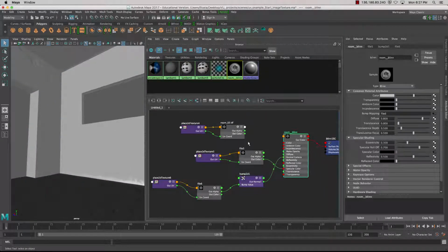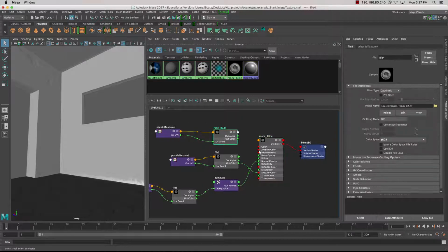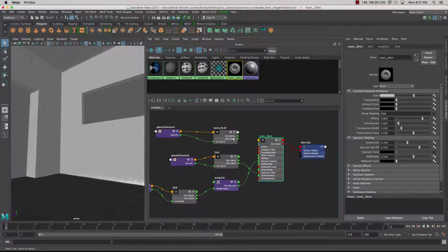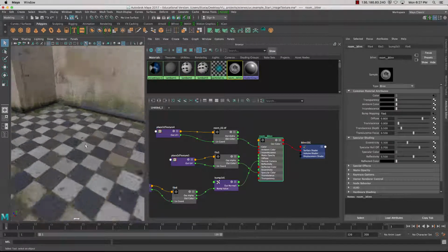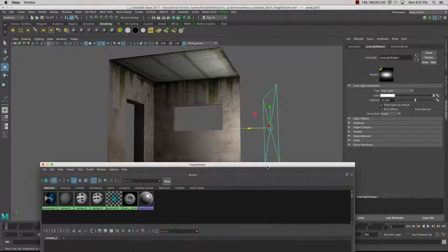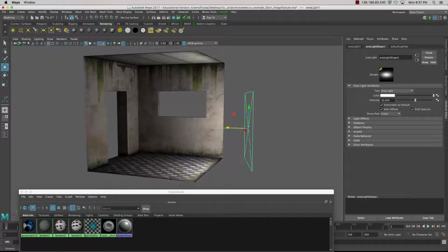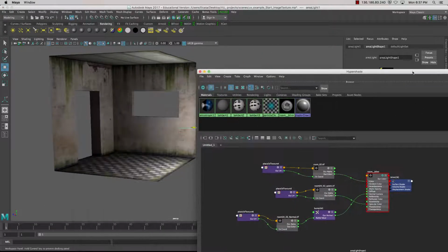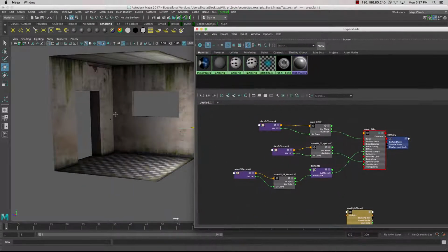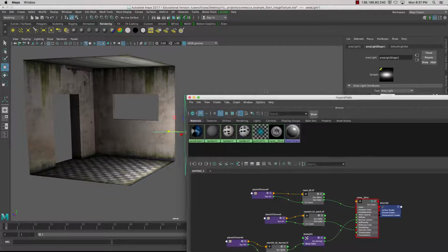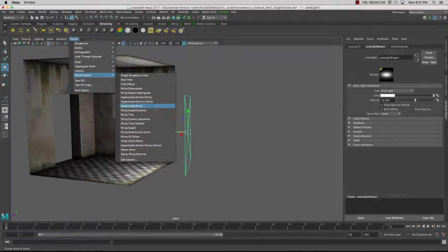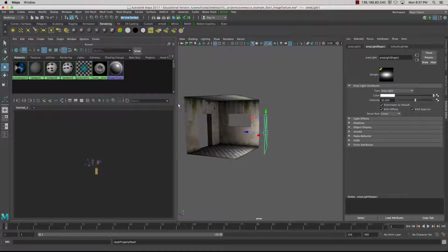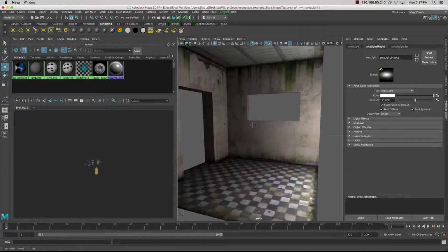So now all I need to do is add the color in again. To do that, I'll just middle mouse drag and drop the room TIFF, place it in, and now we've got all of them lined up. Now what I'm going to do is try some different techniques in adjusting the specular map. To do this, first of all, let me just organize the space a little bit better. We'll go saved layouts, Hypershade and perspective, bring them up like so,